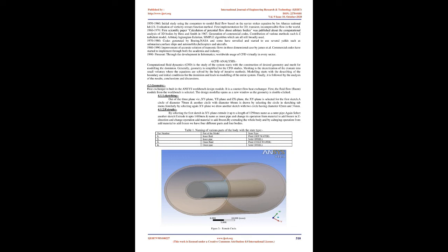Soliman et al. studied steady, laminar, forced convection heat transfer in the thermal entrance region of internally finned tubes for the case of fully developed hydrodynamics. Results were presented for 16 geometries including the local Nusselt number and developing length corresponding to each boundary condition. These results indicate that internal finning influences the thermal development in a complicated way, which makes it inappropriate to extend the smooth tube results to internally finned tubes on a hydraulic diameter basis.